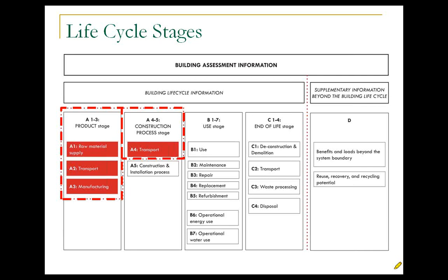One thing interesting about EPDs, if you're only doing a cradle-to-gate EPD, you can only use that EPD for communicating business to business. You are, in theory, not supposed to use these EPDs for communicating this information to consumers. When you do a true consumer EPD, it would be from cradle to grave. So in this case, because it's a cradle-to-gate type EPD, it's used for submittals to design professionals on a project and so forth.